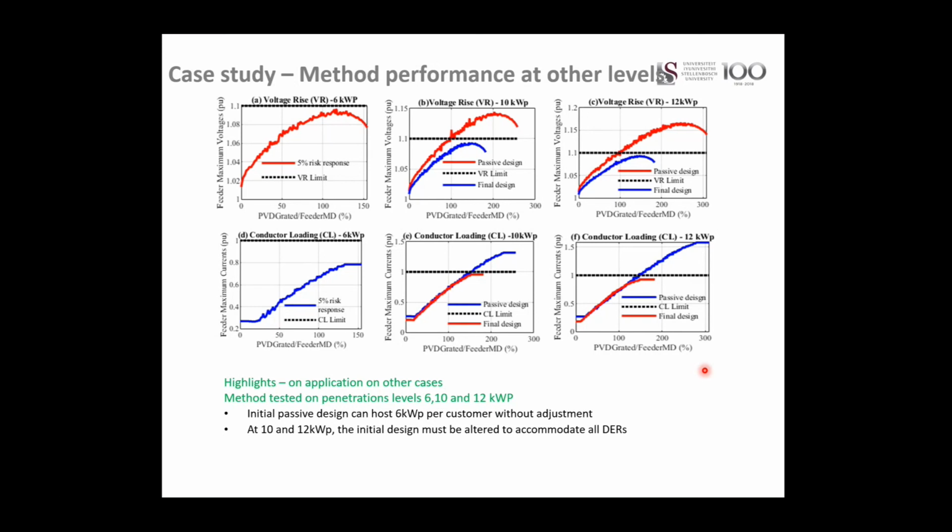They are not required to have voltage control or volt-VAR control capability. So when the sun is there, they just inject on the grid, and when the cloud passes, they are not there, and they don't have the reactive power capability that would assist in stabilizing the voltage on the feeder.